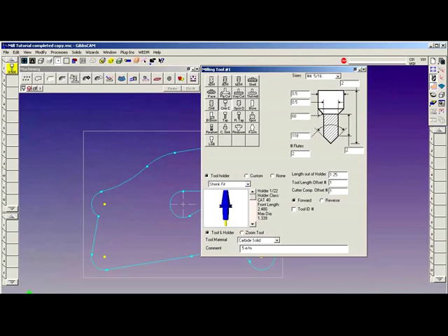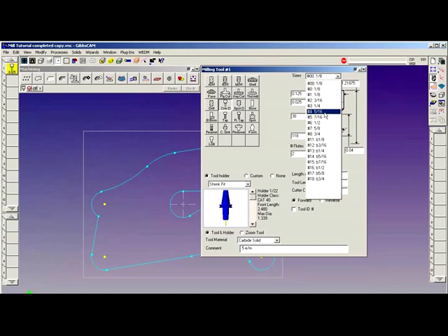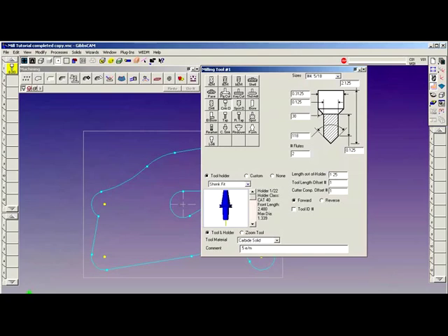Center drills. Center drills are a snap to define. We define center drills based on their size. A double-aught center drill, select it, fills in all the dialogues for you automatically. The reason we can do this is because they conform to a standard criteria. Anytime you pick a number 4 center drill, 5/16, you're going to get the same criteria from any manufacturer.